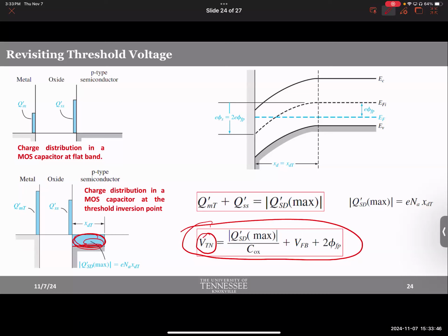And the whole purpose of the transistor is to either turn on or stay off. When it turns on, it represents 1. When it stays off, it represents 0. And in the digital universe, we deal with 1 and 0. If it is on, it's 1, otherwise 0. So basically, it changes the bit entirely from 0 to 1 by changing from being off to on. So the threshold voltage determines whenever your bit will flip. This is how critical it is, right?